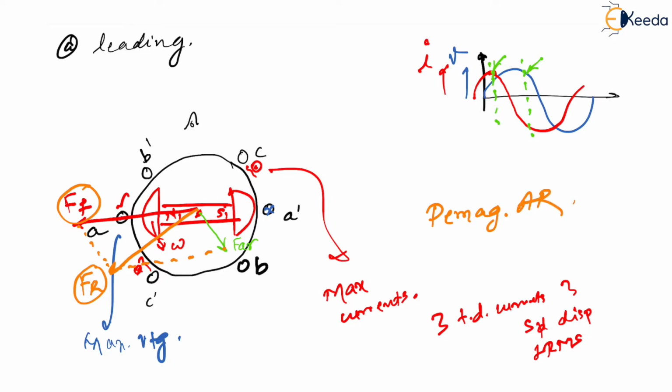Yes. And another thing is, if you see here, since it is entering here in stator, so this becomes south pole of the resultant and this becomes north pole of the resultant, correct? Now, this north of the field and the south of this resultant, they will get attracted to each other. So you will definitely have a torque in this direction, which means now again, if you observe, this torque and this speed are again in the same direction, which is the important necessary property for a motor, correct?